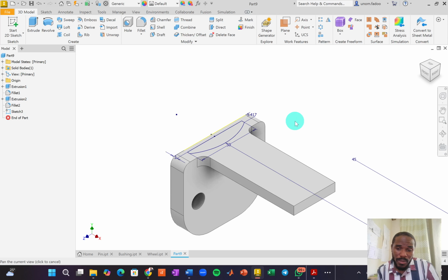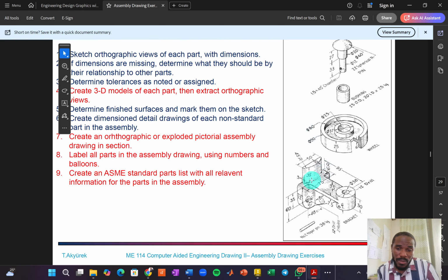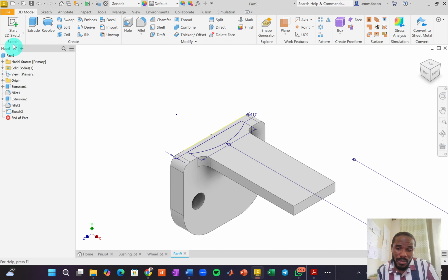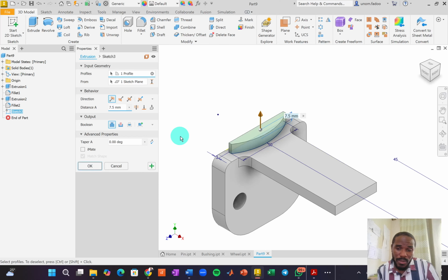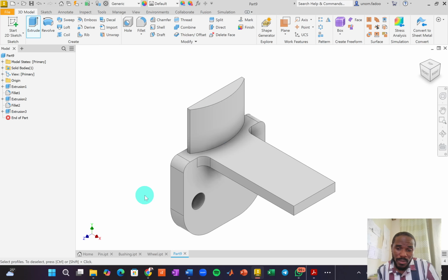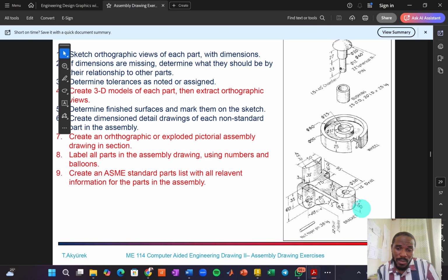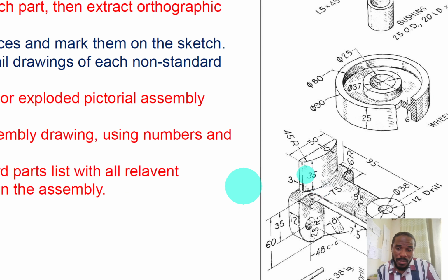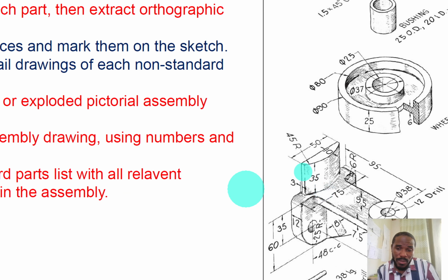Now I'm going to extrude. And remember, I'm extruding by 35. Okay, so I will pick the extrude tool. It has just one feature, so it's just going to select that. So I'm extruding up by 35 and it's going to join the same body as the previous ones. There we go. Are we not getting closer and closer? That looks beautiful, isn't it? It does appear, I don't know whether there's a small fillet there, but I'm just going to ignore it.